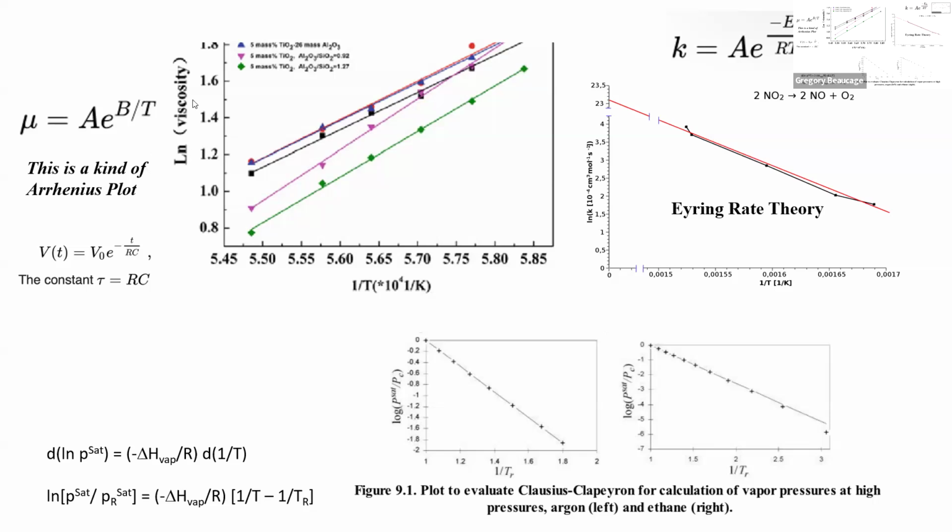So you measure the viscosity, log of the viscosity goes with 1 over T. The slope of this is the energy of activation. If you had two molecules and a third molecule had to squeeze through, it had to push the other 2 apart. It's the energy of pushing the other 2 apart to pop over to the other side and flow. So that's the activation energy; for viscosity it's always log viscosity versus 1 over T, and the slope is the activation energy.